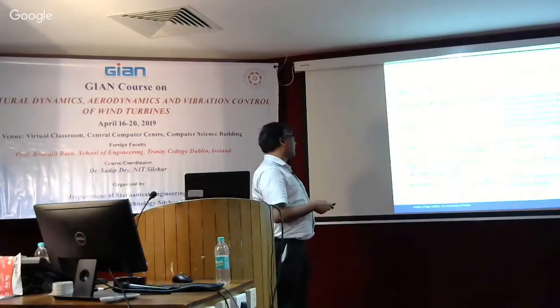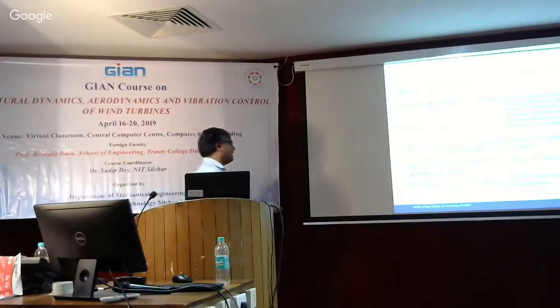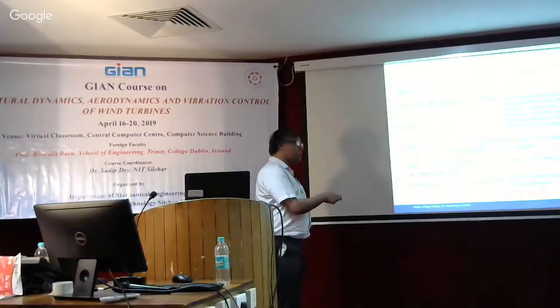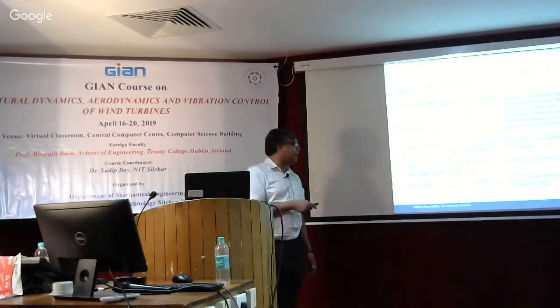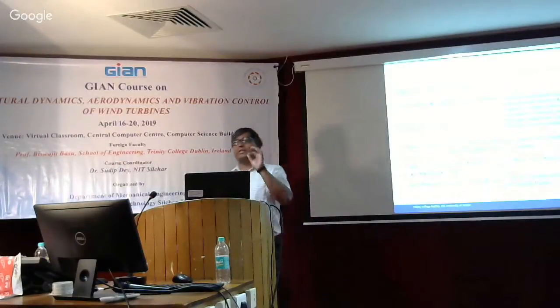So once we obtain the U in the non-rotating frame, we have to get it back into the rotating frame. So we apply the P_U on that, and then effectively we get this minus P_U G_NR star X_NR from the U_NR. And then obviously X_NR also can be related to the rotating frame, which is P inverse X. So essentially now your rotating frame control input, which is the force we apply, relates to the rotating frame displacement and the velocities, which are the states.